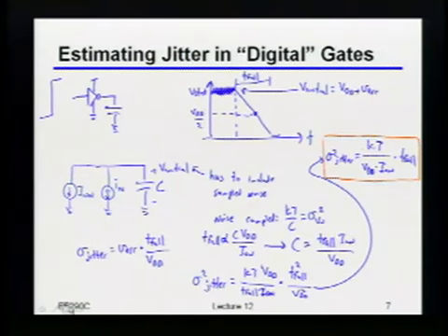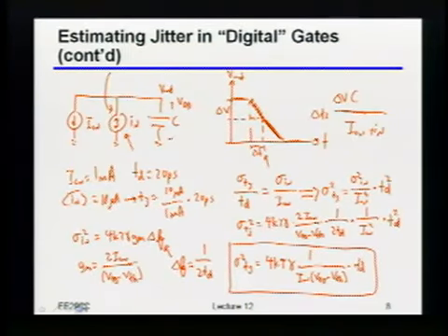Now, it's not that I necessarily use this all the time, but it's actually pretty useful for thinking about how many stages of inverters, or how big of an inverter, I need so that I don't add more than X femtoseconds or picoseconds of jitter into my system. Especially if you're shooting for a very low jitter link, you'll see there's a very small number of low power inverters you could add before these jitter numbers add up and swamp out the entire rest of your system. So just keep that in mind, because it is indeed important.